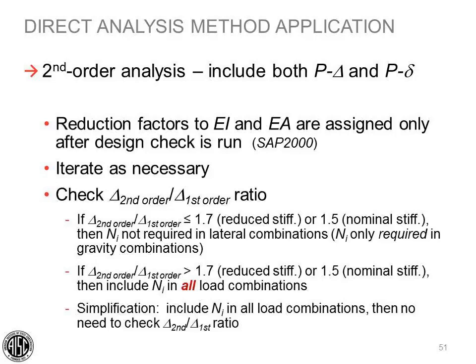If your frame is fairly stiff already, then the secondary effects will be minimal, and you may not have any increases in demands or very low increases in demands. So it really depends on your structure. If you have a flexible structure, there will be increased demands going from first order to second order. If you have a stiff system, then that effect is very, very small. Okay, thank you. Next question.